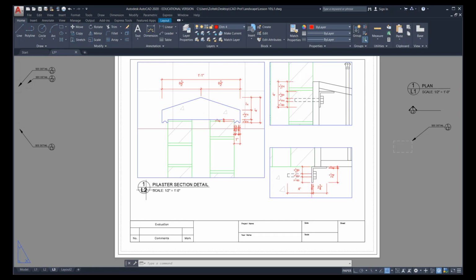Now, why is that significant? When you're using boxes to refer to drawings, these title bubbles should be positioned in more or less the exact same place, so it looks very consistent. This is my stone cap detail. Its scale is 3 inch. So let's change that 1/2 inch to a 3.